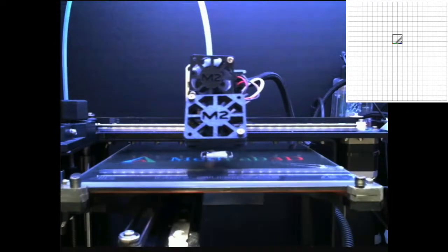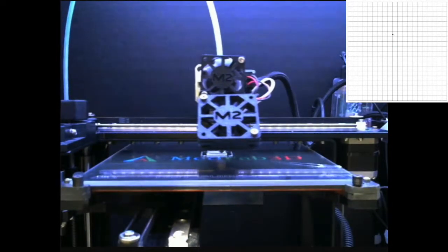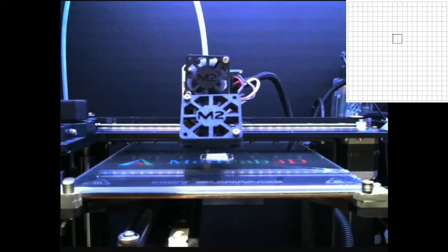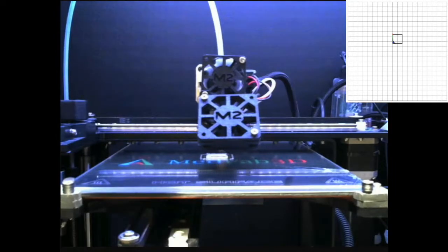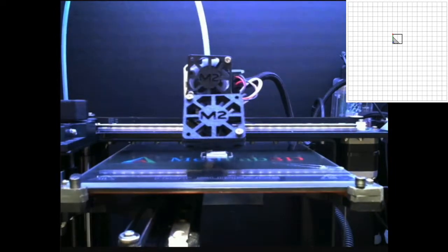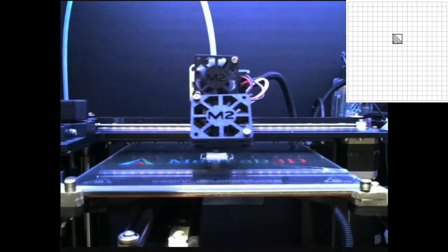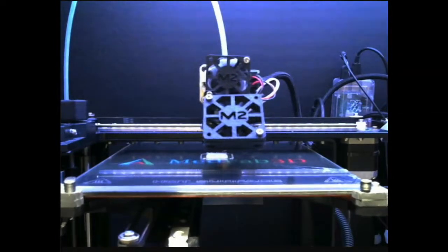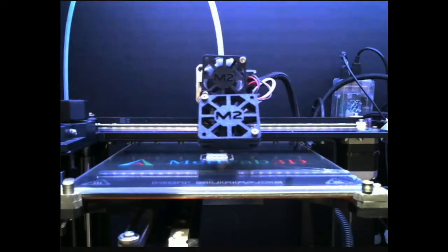The second reason is that when we print the part, it's not a solid fill. In this case, we're using a 30% infill pattern, and you can see that it's diagonal as we're going across the part. This does 2 things. It lowers the overall weight of the part and reduces the amount of material that is used. It also decreases the amount of print time that is involved to print the part.